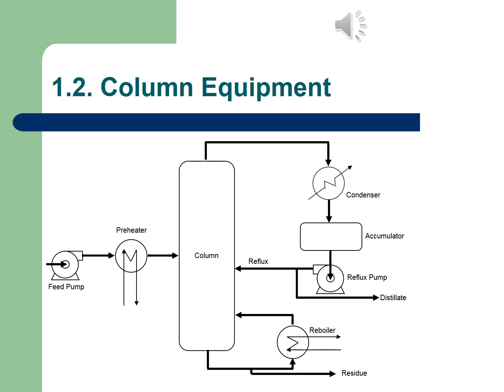Okay, but now if you have industrial process, it will be continuous. So there will be a feed pump, a preheater, the column, okay, a condenser, accumulator, a reflux pump, and also a reboiler. Because usually these columns are fairly large. It can be quite a few meters. Now, the feed pump will actually feed the column. That is the mixture that needs to be separated.